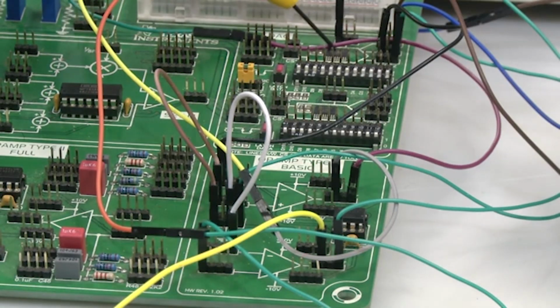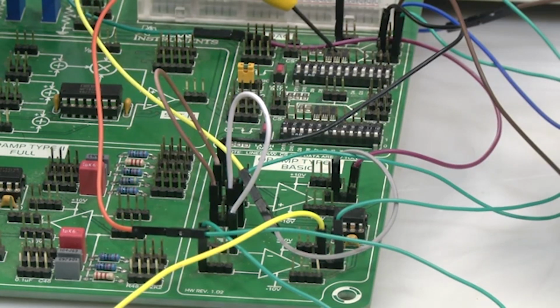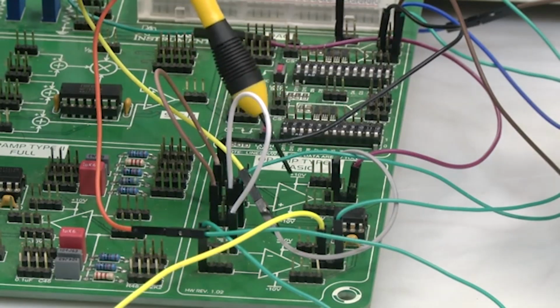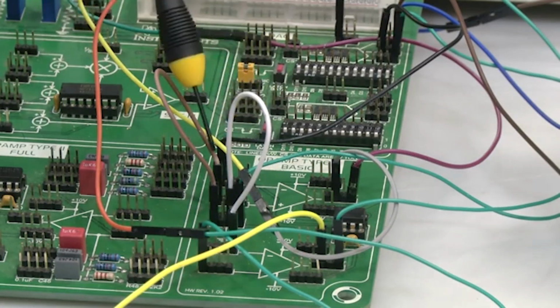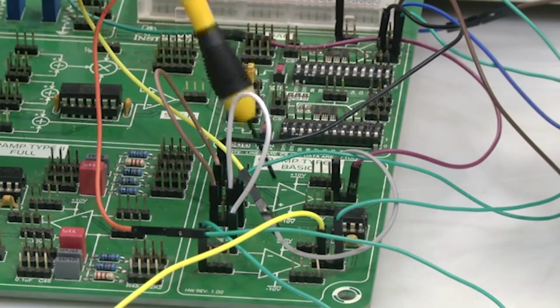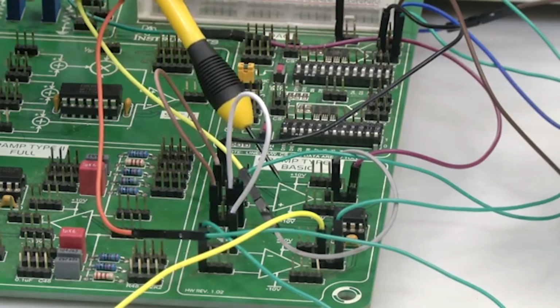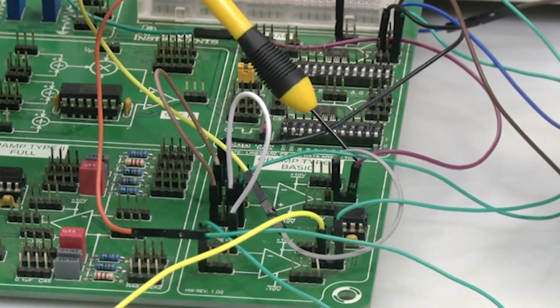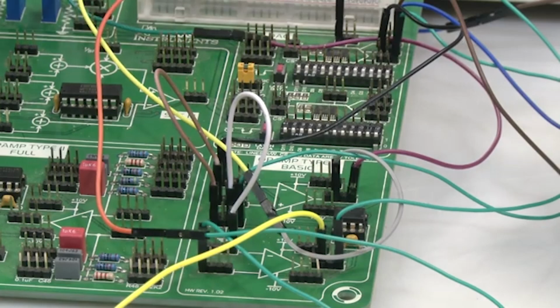So the DAC, which is this one, okay, the DAC is connected and its bit sequences are here, and the output of it, IOUT1 and IOUT2, goes to ground, as well as the positive terminal of the op-amp goes to ground, okay, and IOUT1 goes to the negative terminal of one op-amp, and R feedback goes to the output of that op-amp here, and then both of them are connected through a capacitor here above on this breadboard.